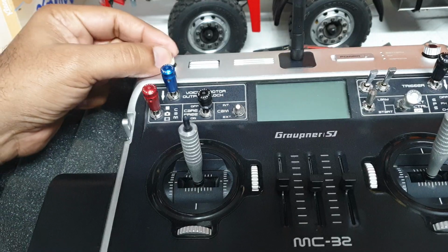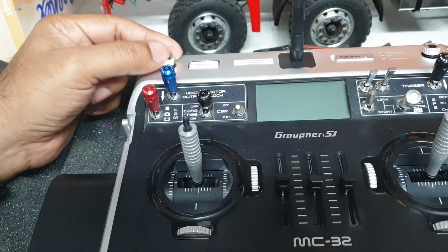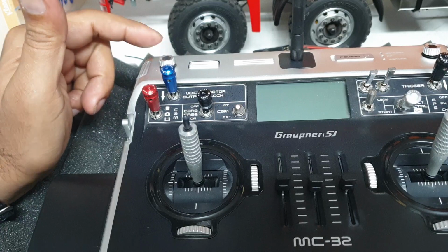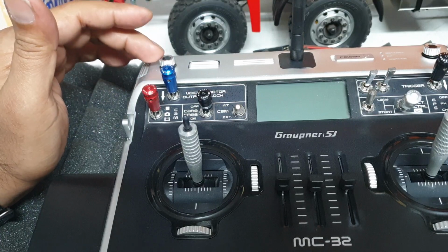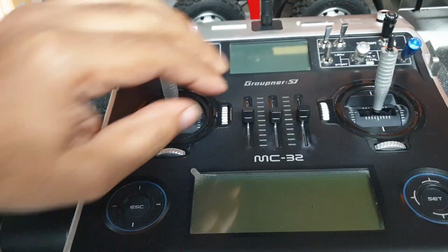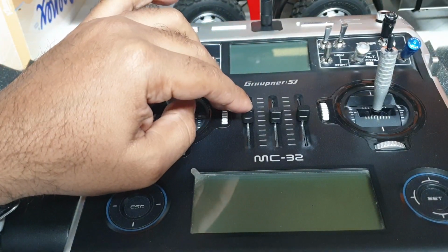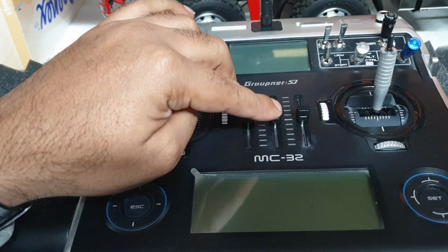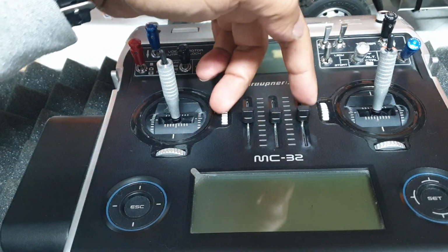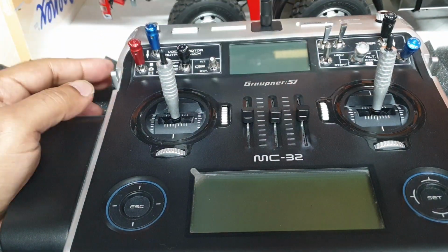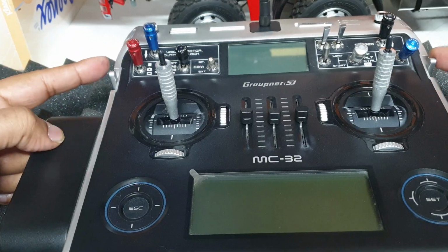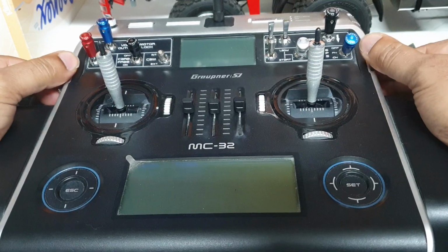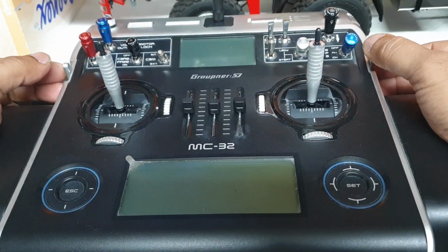What I've done is, I don't know if you can see it up here, this particular switch, I always use it for my pump. It's just easy. So all my models, the hydraulic pump will always be on this particular one, and I'll assign pretty much the same channel to this particular switch. The first one, generally I will use this for gearbox or gears. If I have diff locks, I'll then go into the center. If I have tracks, I'll go to the two extreme ones, or I can even use these two up here for tracks. So it's easier to control the tracks if I have to, depending upon the model.